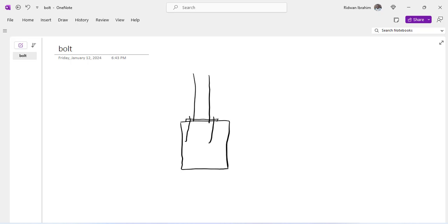Which simply means that when this bolt fails, the base plate is going to shift off the concrete plate. So when your base plate design is correct and your anchor bolt design is wrong, when the anchor bolt fails, the base plate automatically fails, even though the surface area and the thickness are well designed.